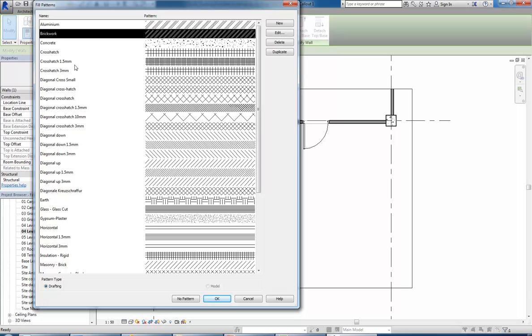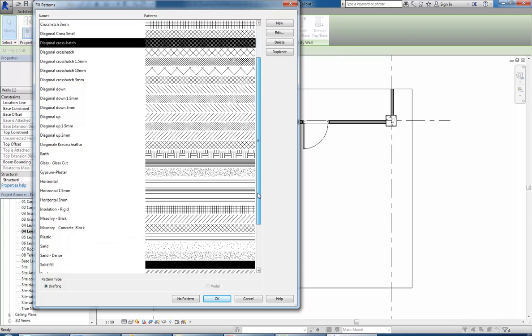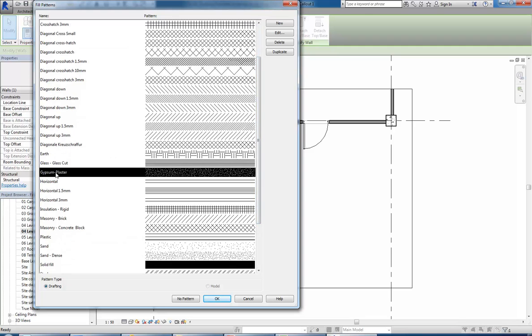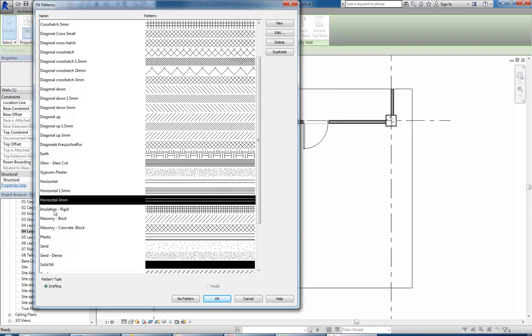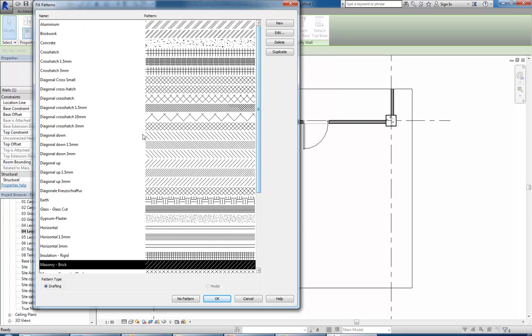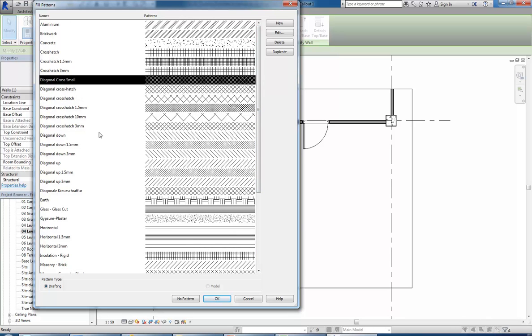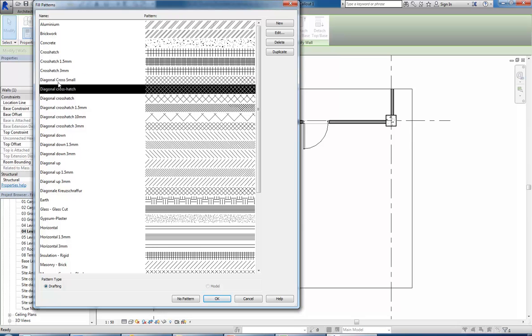It's important to realise these are symbols, so they're not a drawing of the material. They're a graphical symbol, and so for metal, for example, it can be a bit tricky because metal sometimes doesn't have a hatch pattern, but if it does, it's usually just a simple cross hatch. And so you can see there we've got no real indication of the size.